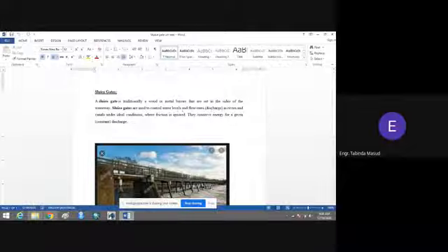It is used to control water level and discharge in rivers and canals under ideal conditions where friction is ignored. Remember, when sluice gates are constructed, the engineers make sure that the bed of the channel at the upstream side and at the downstream side is lined enough to control the friction. We can't say that there is zero friction, but for a good lining, we can assume that there is no friction, and thus we say that the energy is conserved, meaning the energy remains constant.